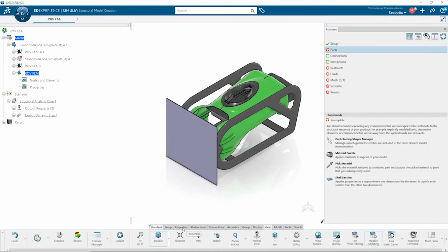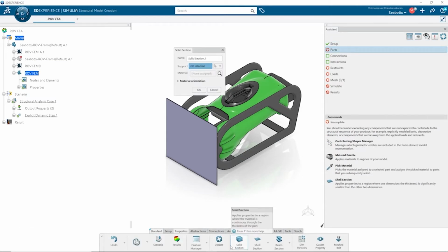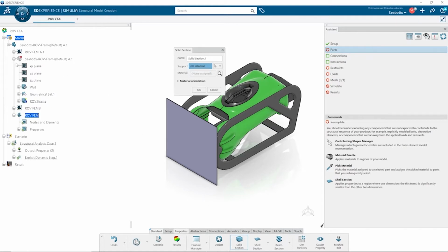Simulations are just as accurate as the material. With section definitions, we not only define them with a simple search, but also include its behavior. With many behaviors available, we can simulate just about any structural analysis. Let's finish it off by defining the rigid body behavior of the wall.